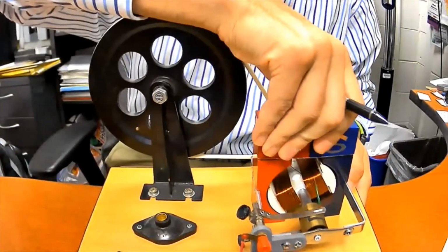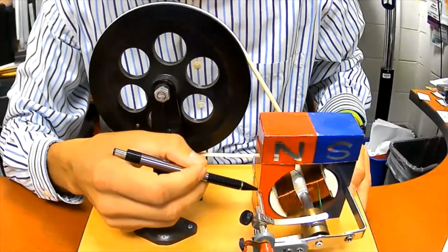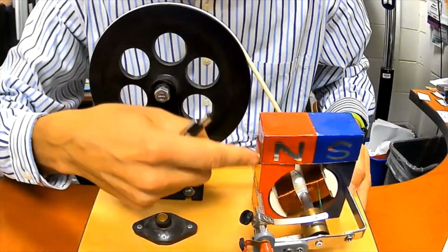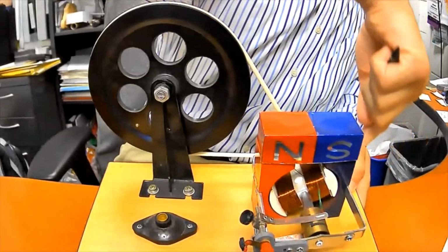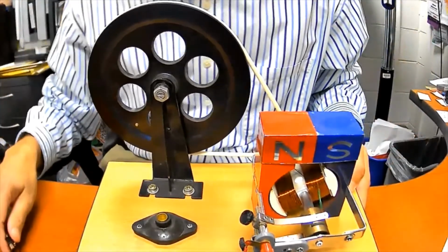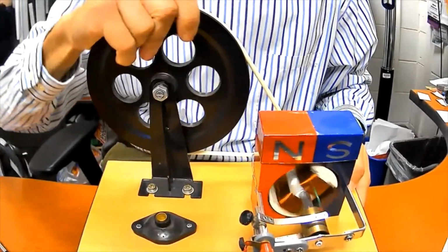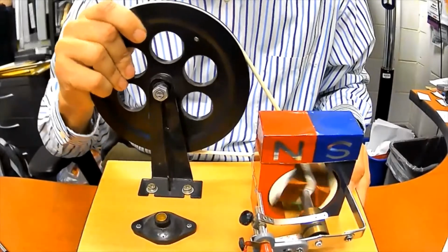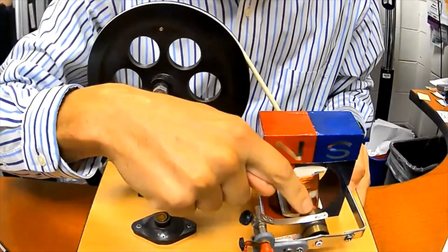And we have our magnetic field, and we have our material of steel right here that has a high magnetic permeability. So this whole side is the North Pole, and this whole side is the South Pole. So this is a 2-pole generator. We have an armature inside here, and as I rotate this, the armature rotates around. And what I want to focus on right now is the slip rings and the split ring commutator.